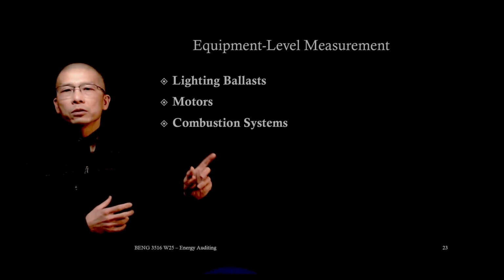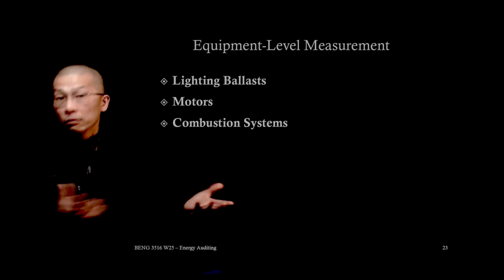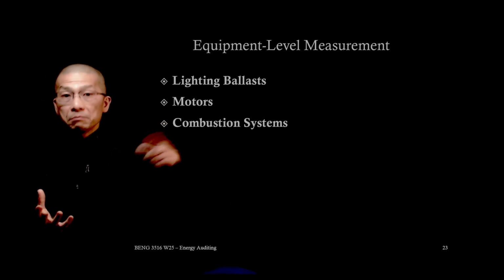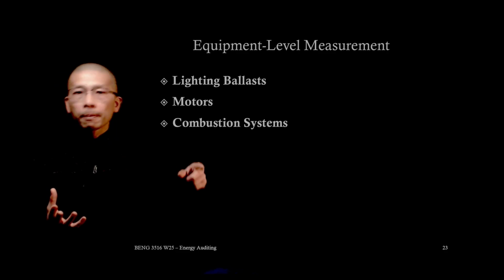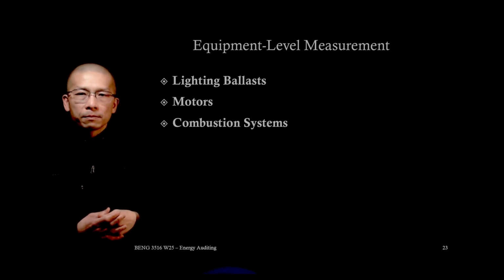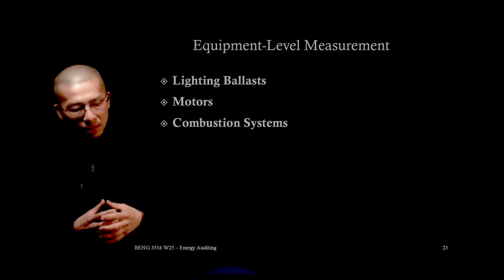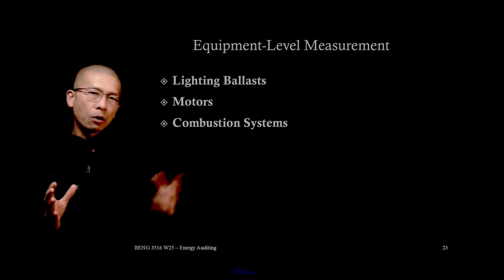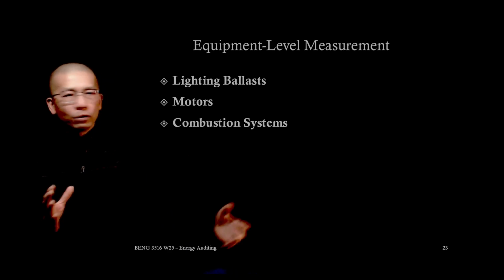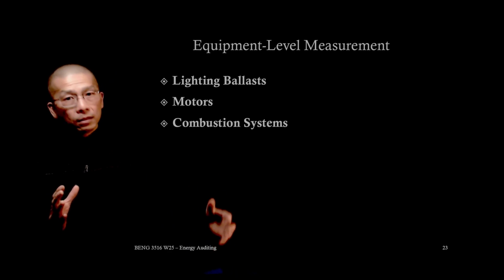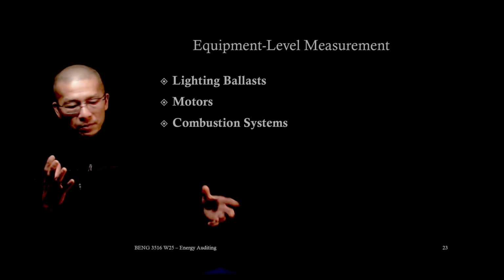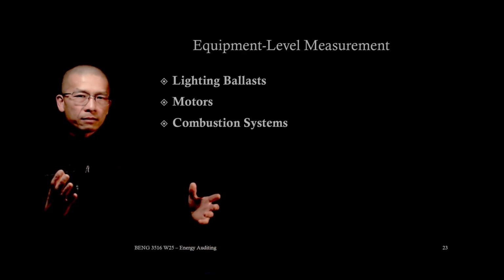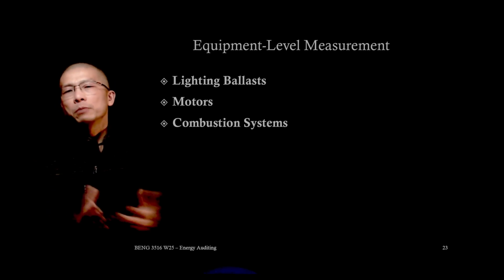Motors, we check for voltage, current, power factor of course, and sometimes the speed as well, to calculate the motor efficiency. And we want a motor that is properly sized, because an oversized or overloaded motor, meaning undersized motor, can waste energy and shorten equipment life.